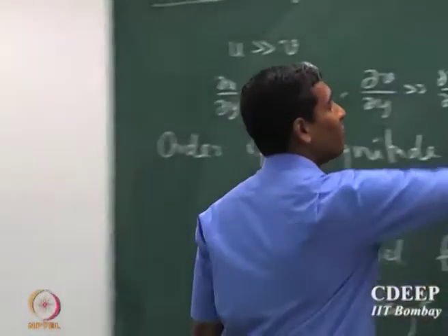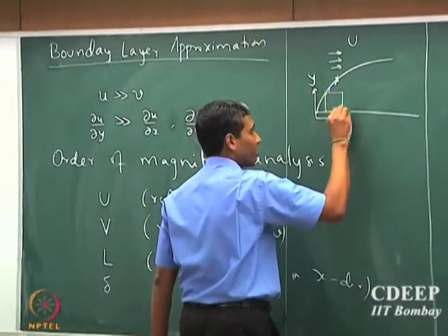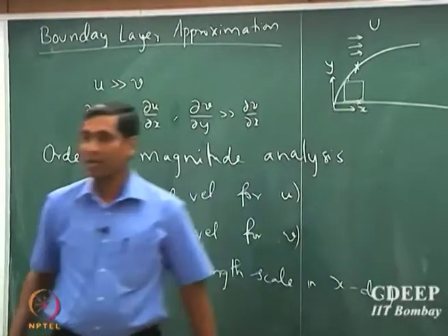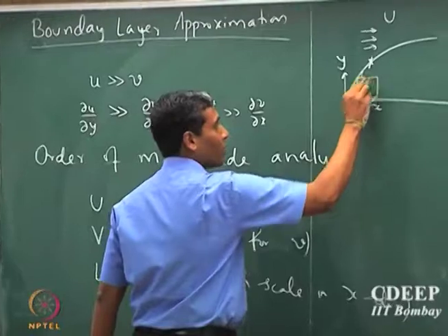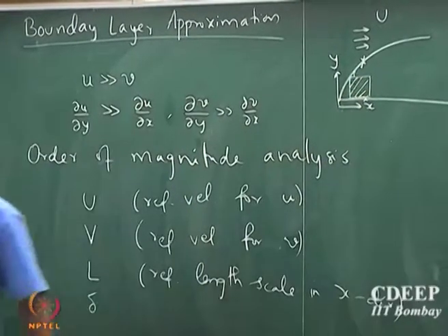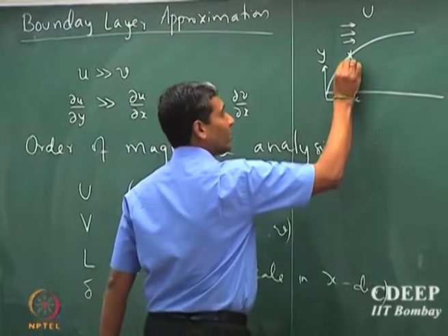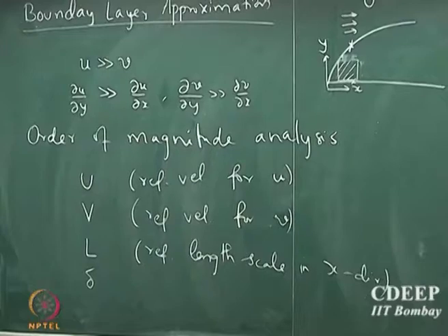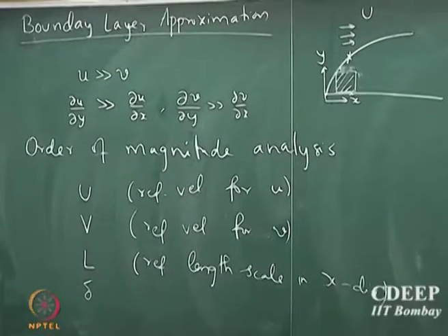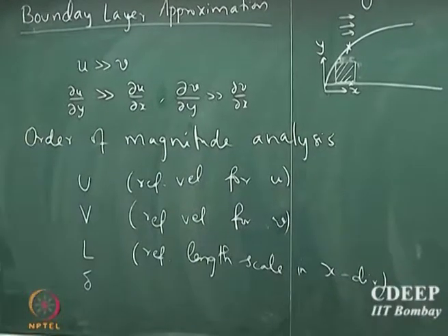No, you will not, because if you write a continuity equation, with this as your control volume, here you are definitely going to see fluid moving out of the control volume, because this is inside the boundary layer and the fluid stream is still experiencing the friction offered by the interface.